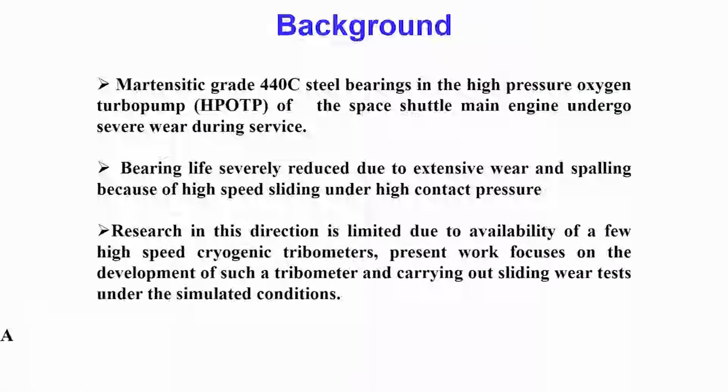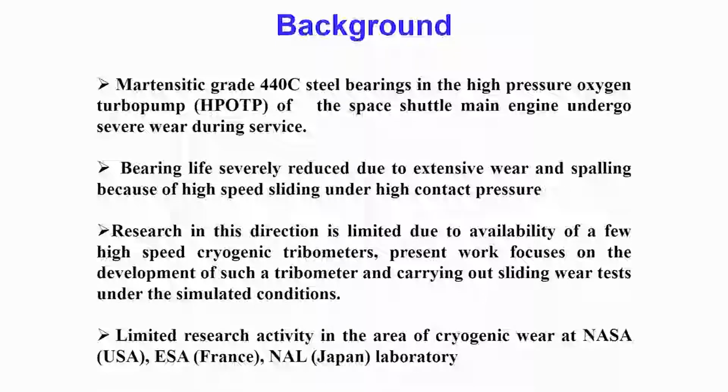So, typically for cryoturbo pumps, which are used in the space shuttle main engine, those kind of very critical engineering engines, they require martensitic stainless steel bearings, and this martensitic stainless steel is typically 440C grade. At present, bearing life is restricted because of the extensive wear and spalling, because of the high speed sliding conditions under high contact pressure.